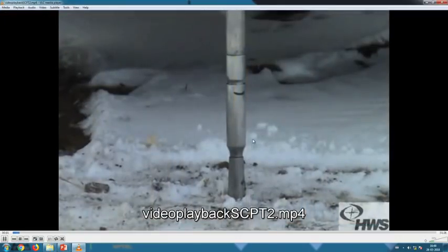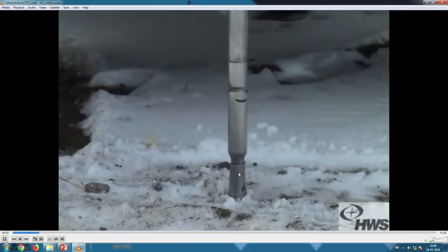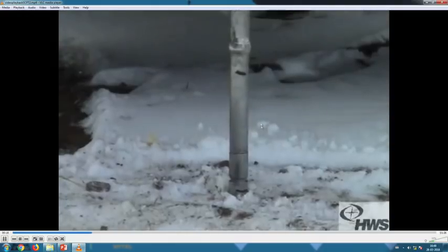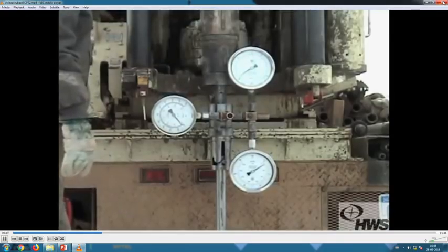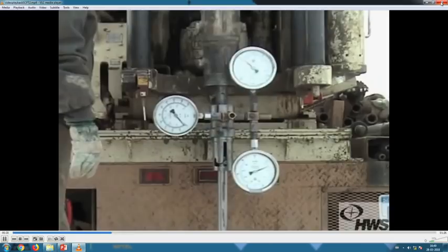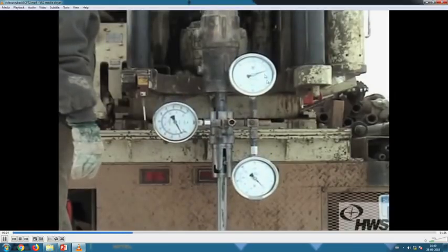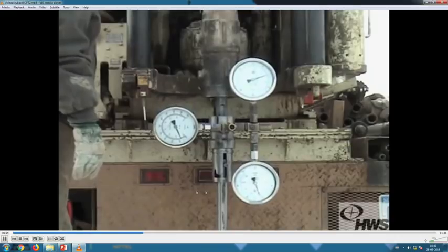I have the same video. First we measure the cone resistance, then the total resistance, and finally, if we subtract the cone resistance from the total resistance, we get the friction resistance. So, these are the testing methodology. Here we are measuring the resistance; this is the instrument, and it is pushed into the soil.